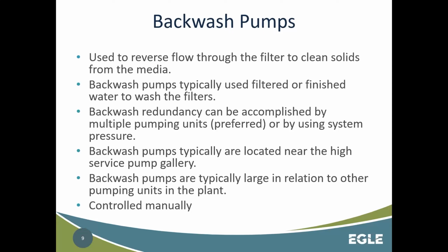We're turning those pumps on, we're reversing the flow, we're pushing through that media, we're getting all those organics, that filtered media that we're filtering out, suspended, pushed out, and dealt with and treated at a later phase. The backwash redundancy can be accomplished by multiple pumping units or by using a system pressure.